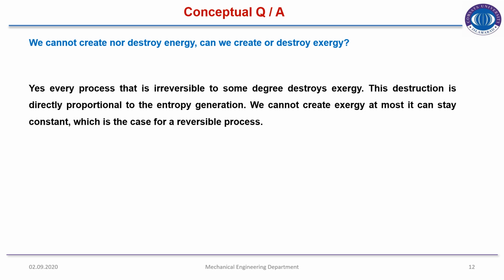We cannot create nor destroy energy. Can we create or destroy exergy? That is another conceptual question. The answer is yes, every process that is irreversible to some degree destroys exergy. This destruction is directly proportional to the entropy generation. We cannot create exergy; it remains constant in the case of a reversible process.